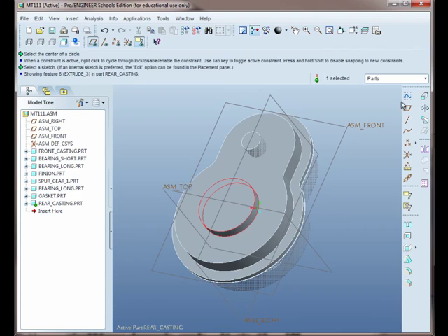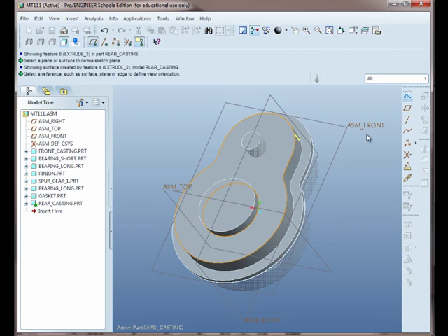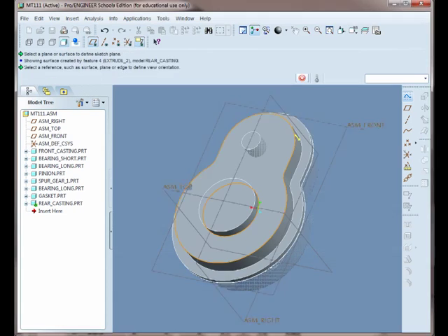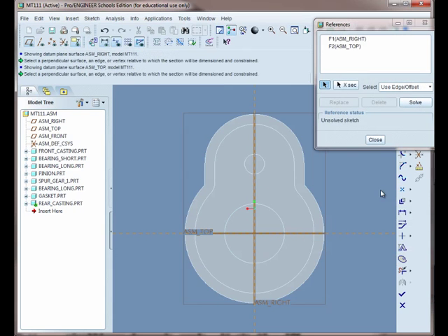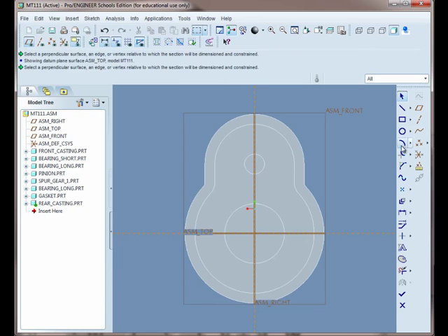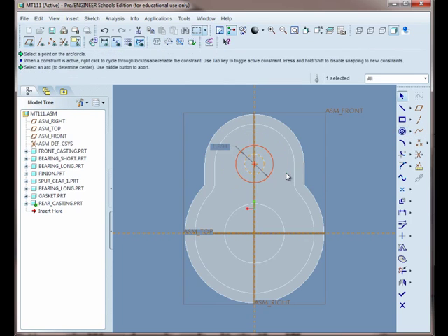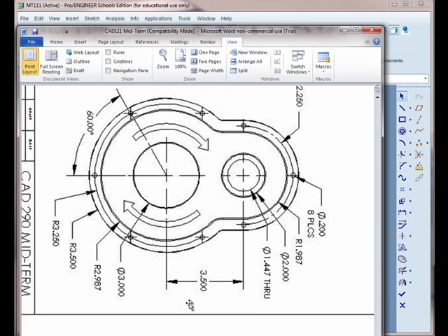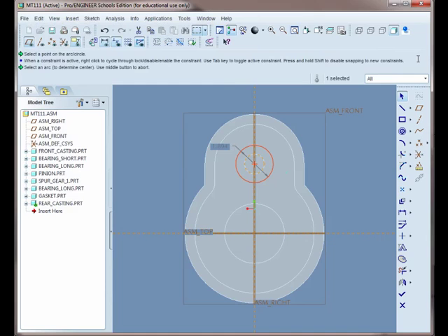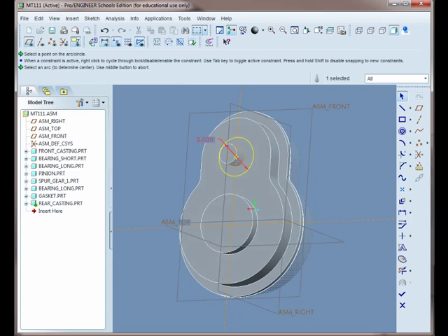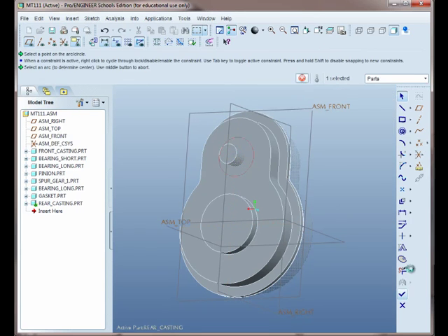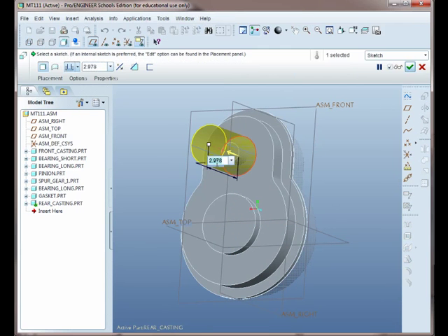The last feature here for an extrusion, we select that face to start a sketch on. Again, vertical and horizontal planes can be used for the references. And we need to draw a circle here. Now, what I would suggest is using the concentric circle tool. Select this edge and drag it out. In the middle, click a couple times. And this diameter needs to be 2 inches. And this gets extruded 3/4 of an inch. So 0.75.